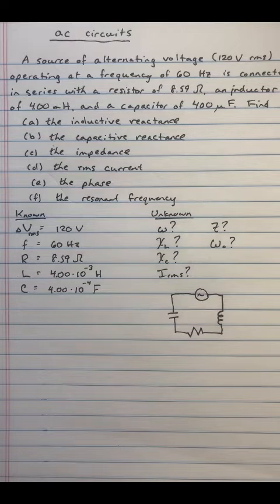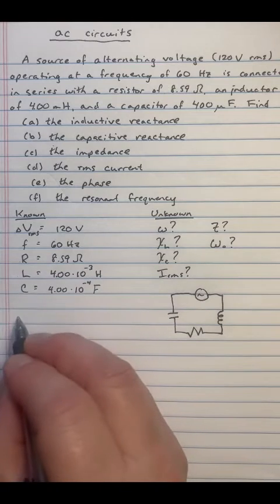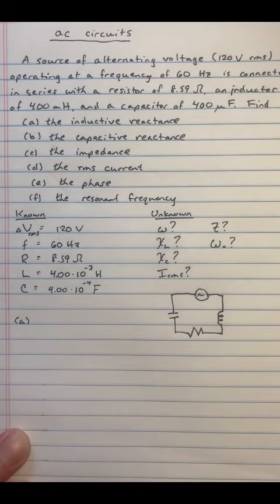So it acts like a resistance in that there's a pushback to keep current from flowing, but it's not resistance because, at least in ideal cases, there's actually no loss of energy. So instead of calling it resistance, we have a different name for it. It's called reactance. The coil reacts to the presence of a changing current and a changing voltage.